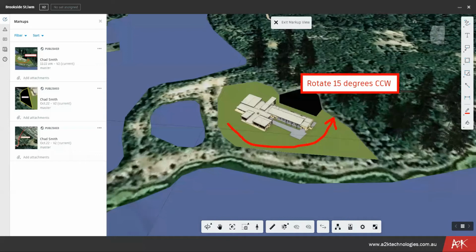But even better is when we view it inside of BIM 360 itself. Here we can see inside BIM 360, utilizing Autodesk's browsing technology so that it can view models directly inside the web browser itself, I have the same model information, which in this case has a range of markups applied to it. It could additionally have some issues applied as well if need be. But the point is that this information is now readily available through a web browser to non-Infraworks users so that they can now contribute into the workflow and the feedback process. And we'll talk about markups and issues a little bit later on.